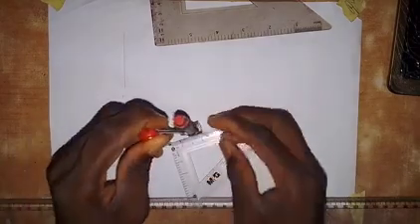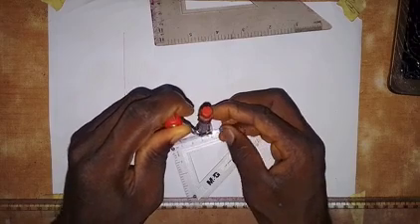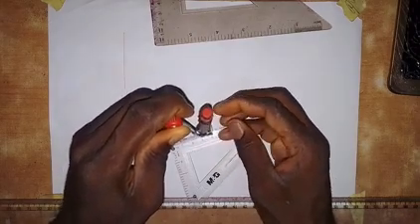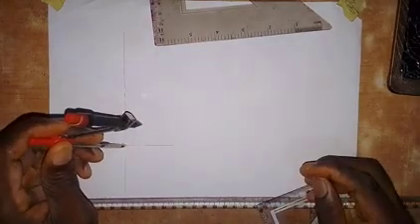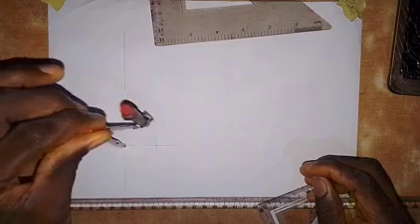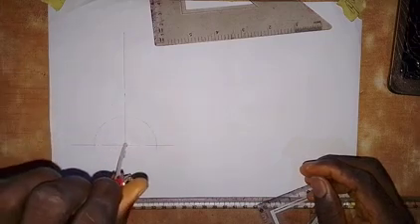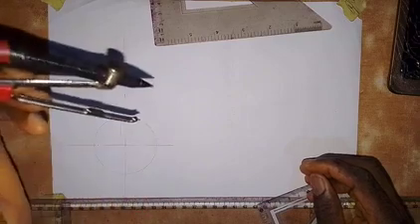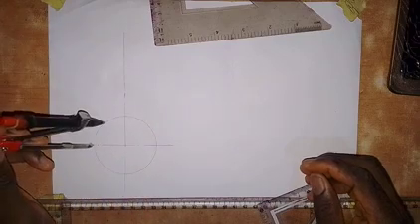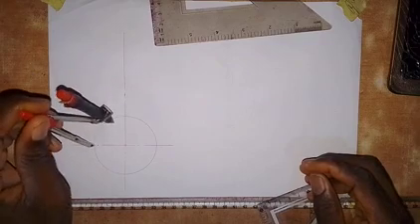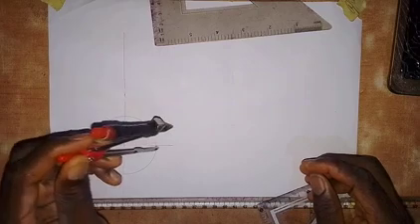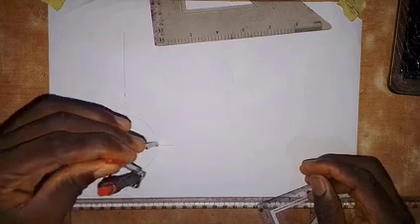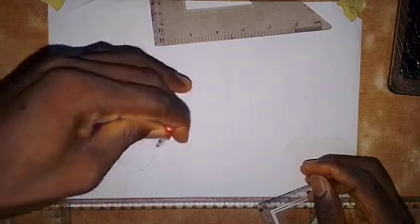Alright, so then we are going to take a measurement of 30 millimeters. If the distance across corners is 60, you take 30 millimeters. Put it at this point here, and then you draw a circle. I'm not going to make the circle more visible, so it's okay like this. I believe you can see it. Then with the radius that I used to draw this circle, you put the pinpoint here, then draw an arc up and down the circle, then put it at this point, and draw an arc up and down the circumference of the circle.